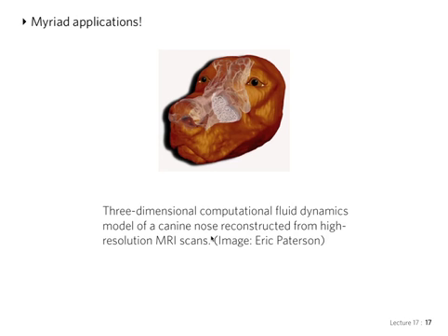So the myriad applications, the final one before I let you go to your next class, is this case of what's called the artificial nose. It was a study done by taking MRI scans of a canine nose, and they did a CFD simulation of all the flow inside this very complicated labyrinth of passageways, and were able to identify the place in the nose that was very important for the capacity of the nose of a dog of detecting really trace amounts of a substance, thanks to this complicated flow that they have in their nose.